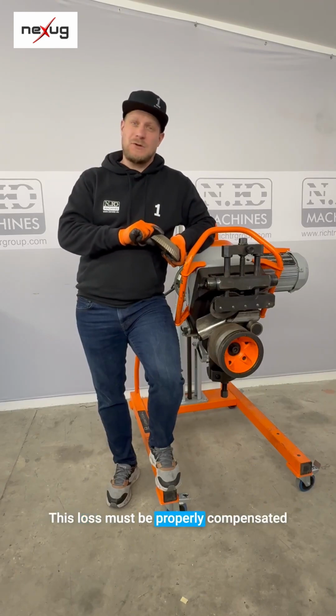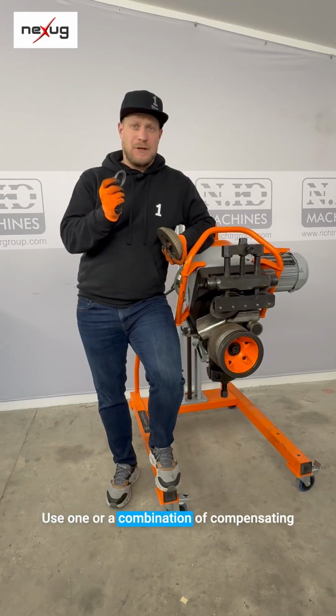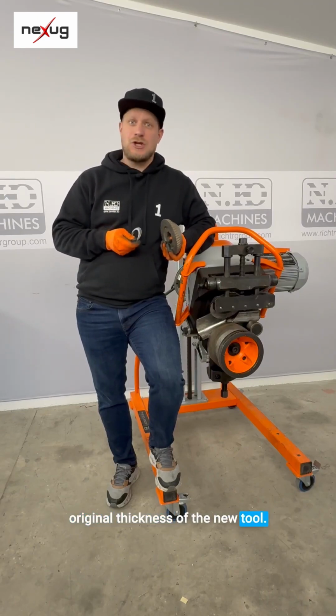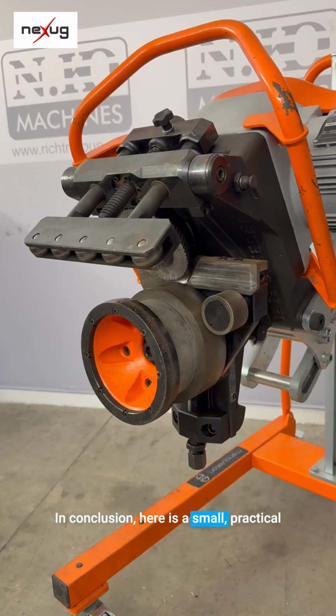This loss must be properly compensated with the attached washers. Use one or a combination of compensating washers to carefully achieve the original thickness of the new tool. Please bear in mind that the final thickness, including the washers, must not exceed the original thickness of the new tool. In conclusion, here is a small practical tip for the more demanding user.